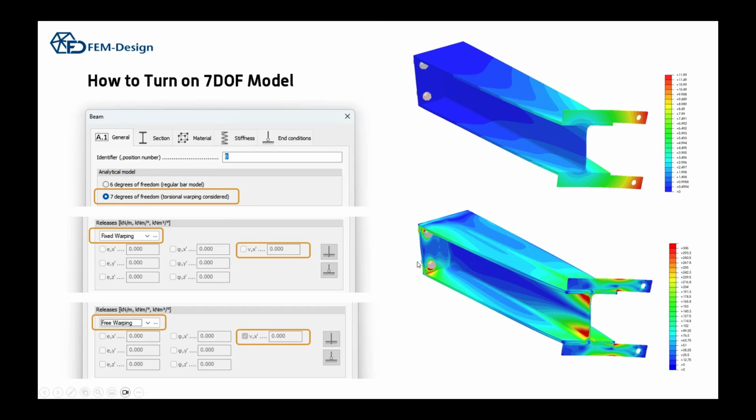Then there's a few other properties. First of all, because we have a warping, we also had to set how this beam is coupled in this end and thus this end, and we have one new degree of freedom what we have to define. This is V here, and we have to define V in the beginning and in the end of the beam. And of course we can build these library items as before.